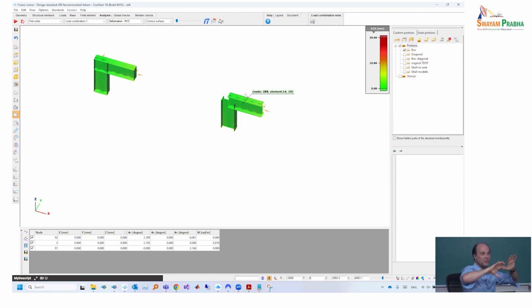We are releasing it from this exercise, and we are enforcing a certain prescribed behavior to the connected elements, because we know what will happen in case of such a box configuration. The beam element doesn't know. We believe that we know more, and when the engineer selects this topology, it basically gives additional information to the beam element-based model, which is not stored and not included in the beam element, about the way the deformation should be transferred. And we solve this transfer not by the beam elements themselves, but by additional constraints transmitting the deformations the way we want.